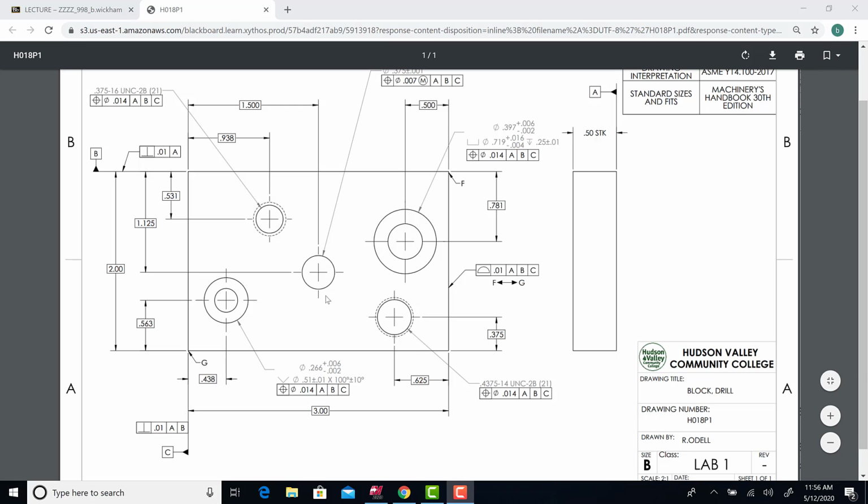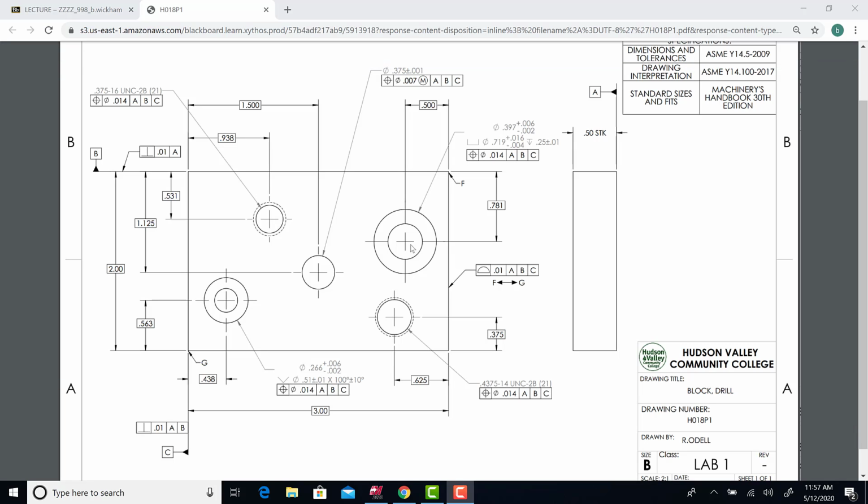Okay, so now we're going to work on the counterbore hole in the upper right. We're going to do offset trim on this. What I mean is I'm going to offset some lines. I'm going to put the two holes at the center of that line. I'm going to delete these other lines to show you that method. We could use the method we did here, or here, or here. These two are similar to the one we just did, except now I want to extrude down a 1/4 of an inch.